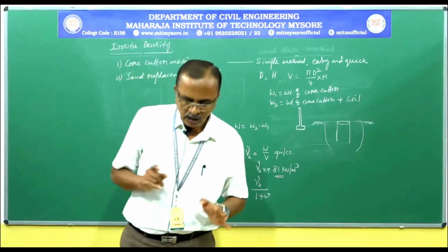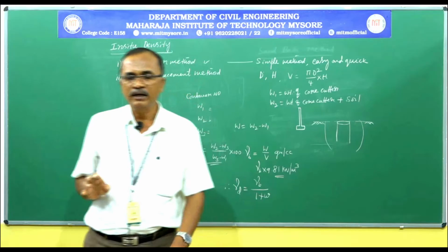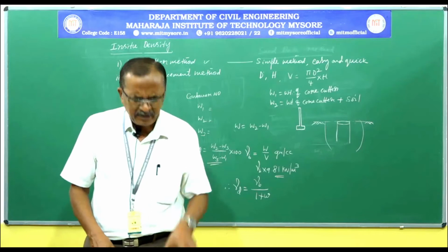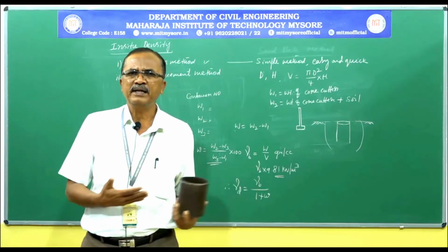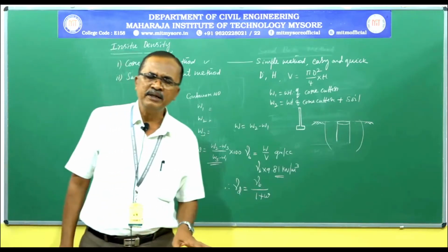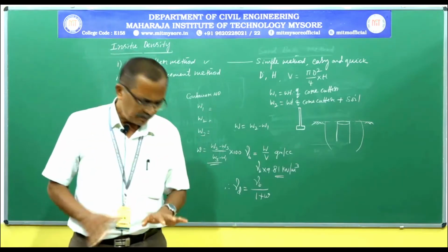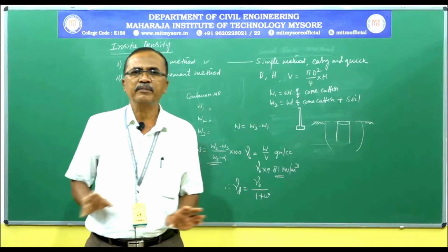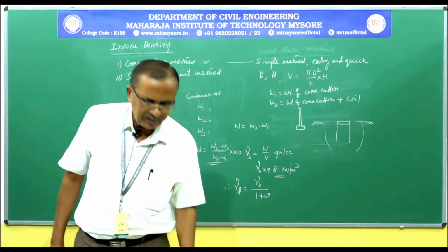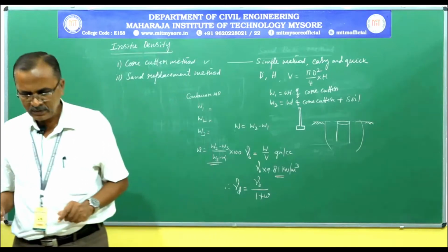It is suitable for soft clay soil and it is not suitable for sandy soil and gravelly or boulder soil. In sandy soil, even if it drives comfortably, we cannot obtain the sand, it is of no use. In gravelly soil or boulder soil, it will damage the cutting edge of the core cutter. Hence, even if it is possible to perform and complete the experiment, you cannot get back the correct value of the soil removed from the site. This is the limitation of the core cutter. So, it is suitable only for soft clay soil.